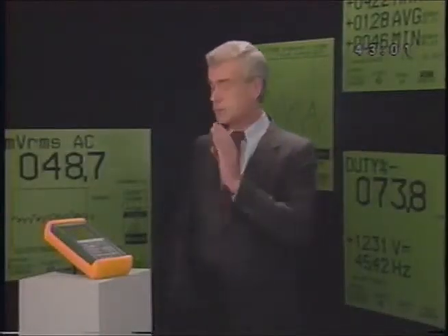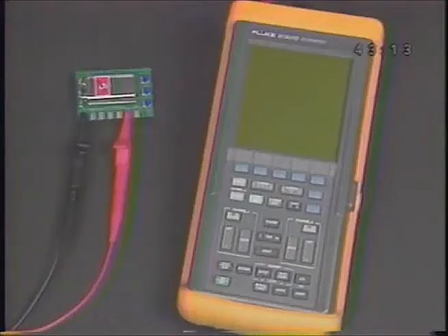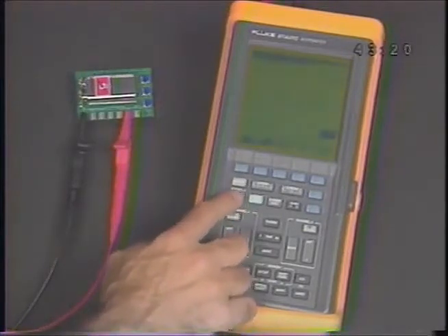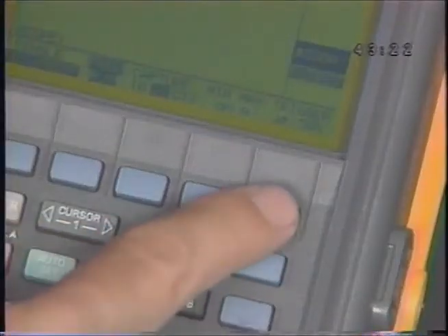In this exercise, you'll learn how to freeze the display and use Scopemeter's cursors to measure and display a signal's pulse width. Set the simulator as shown in the simulator exercise for Lesson 3 in your workbook. This should give you about a 50% duty cycle. Connect Scopemeter to the simulator. Turn Scopemeter on and press Scope. Press the trigger at 50% soft key. That sets the trigger level midway between the highest and lowest voltage levels being displayed. Sort of an auto set for trigger.